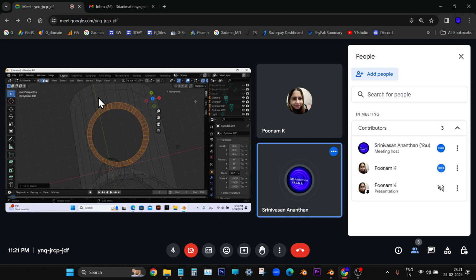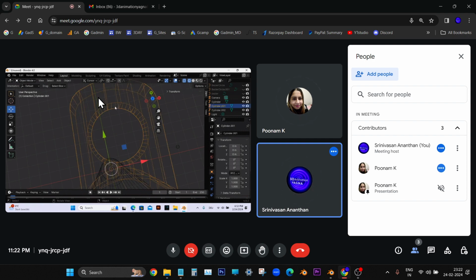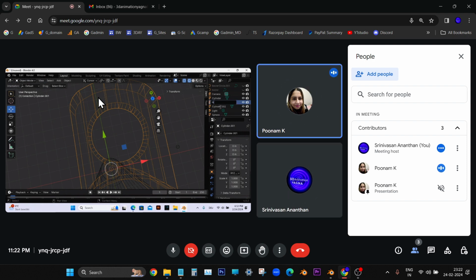Now you can press Alt A and come out of this. That is deselect. Now go to object mode. You can select this hook object. No, they are one single object. Just do pick selection. Yeah, that is all. Now name it in the outliner as hook object, hook mesh or something. Hook. Yeah, that's all.